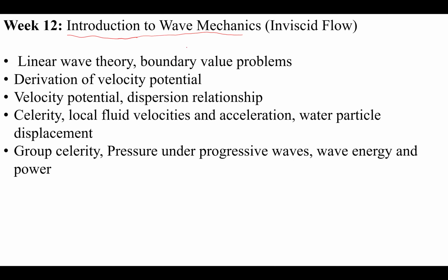All the conversation we cover, or sir has covered, is for inviscid flow. So in week 12 on linear wave theory, there are lots of topics: the linear wave theory, boundary value problem, derivation of velocity potential and velocity, what the velocity potential is, dispersion relationship and celerity, local fluid velocities and acceleration, water particle displacement, group celerity, pressure under progressive